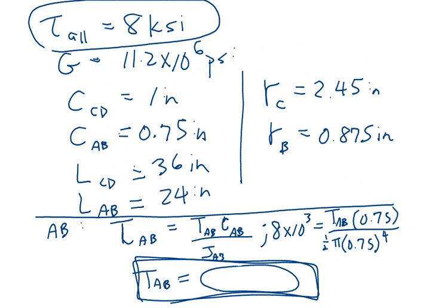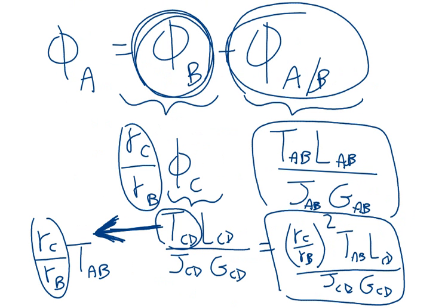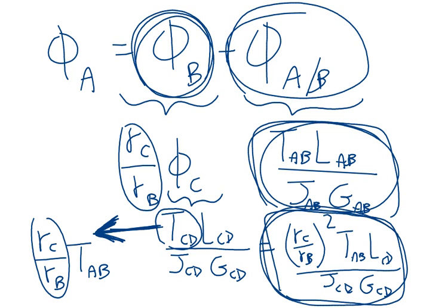All right, so once you have these torques, they ask you to find the angle of twist, or the amount of rotation in end A. And that's where you do this term plus this term, where you use that torque AB that you found in part A in here and in there. And that will give you an answer for the rotation at A in radians. So what you need to do is convert that to degrees. That's usually how you'll want to express an angle of rotation.